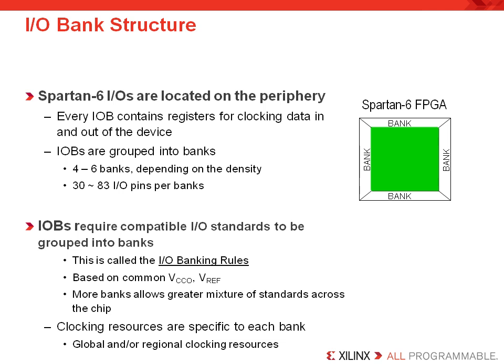The input-output blocks, or IOBs, interface between the FPGA and the outside world. They are shown in this diagram on the periphery of the die. IOBs are grouped into IO banks located on each edge of the device. The IOBs contain registers and some specialized resources, but the main purpose of the IOBs is to clock data in and out of the FPGA.